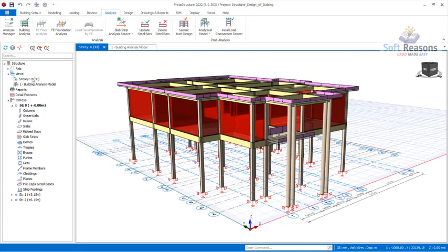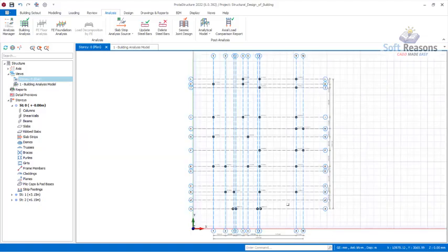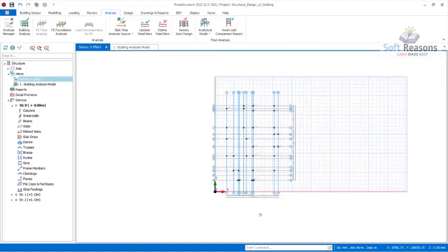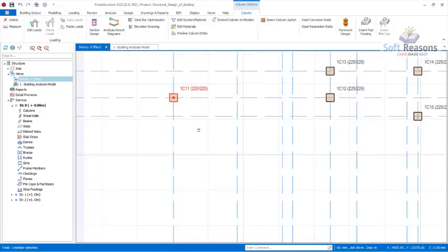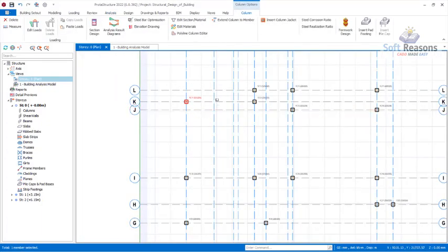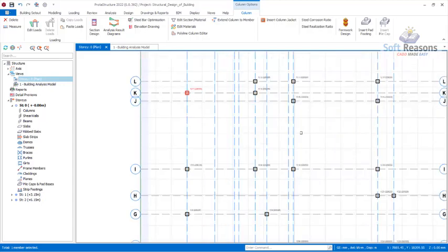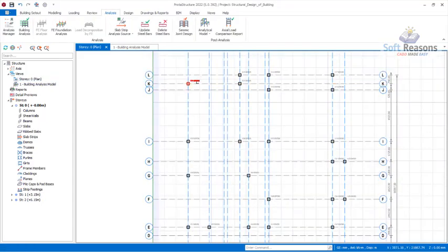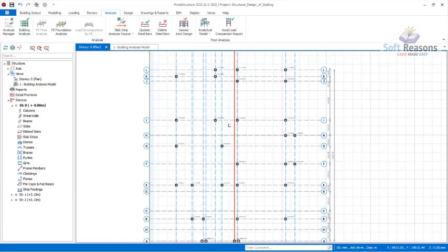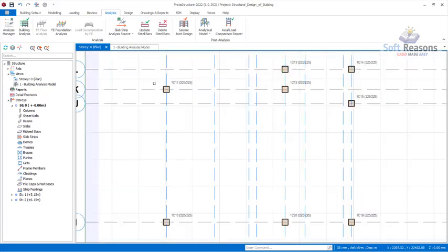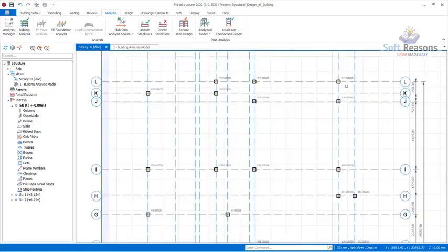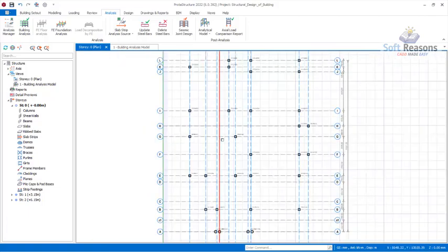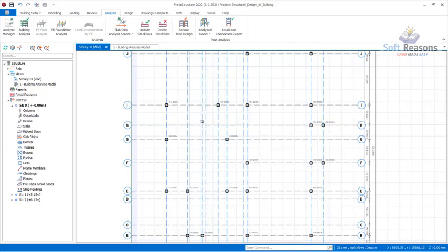We proceed. Navigate to the plan view of that foundations level, at this plan view right here. So you just have to select any of these foundations, sorry, any of these columns, and then insert your foundations. But before then, you can actually enable the axial load that is coming to the foundation from each of these reinforced concrete columns. So I'll be able to enable that.